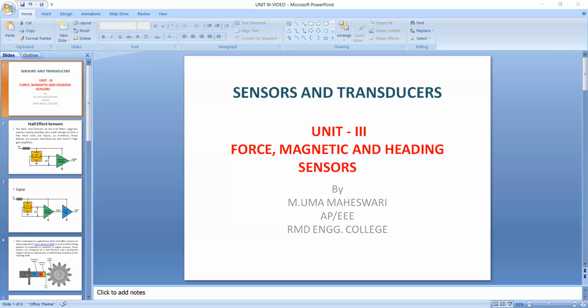A few disadvantages of Hall effect sensors are: they are not able to measure current flow at a distance of more than 10 centimeters. A solution to overcome this is to have a very strong magnet that can generate a wide magnetic field. The accuracy of the measured value is always a concern because external magnetic fields may affect the values. And the third disadvantage is that high temperature affects the conductor resistance. This will affect the charge carriers' mobility and the sensitivity of the Hall effect.